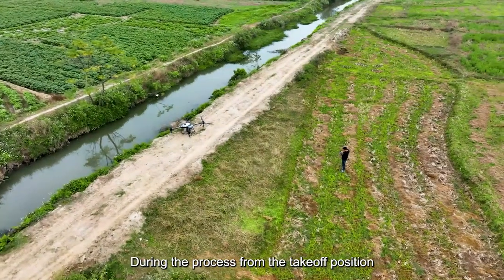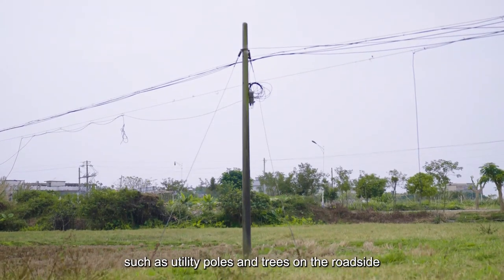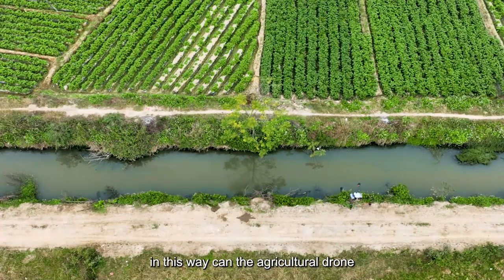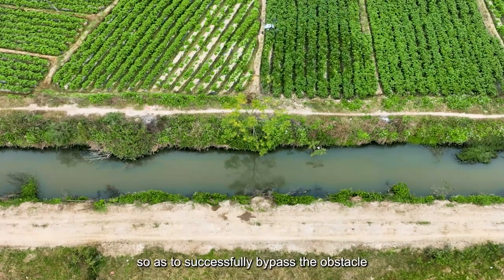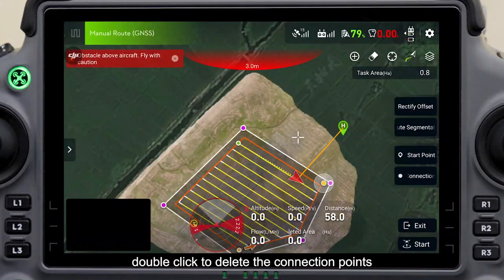During the process from the takeoff position to the break point, if there are obstacles such as utility poles and trees on the roadside, click the Connection Point icon on the right and add a connection point using the crosshair in the high-definition map. In this way, the agricultural drone can fly from the takeoff point to the connection point and then fly to the break point so as to successfully bypass the obstacle. Double-click to delete the connection points.